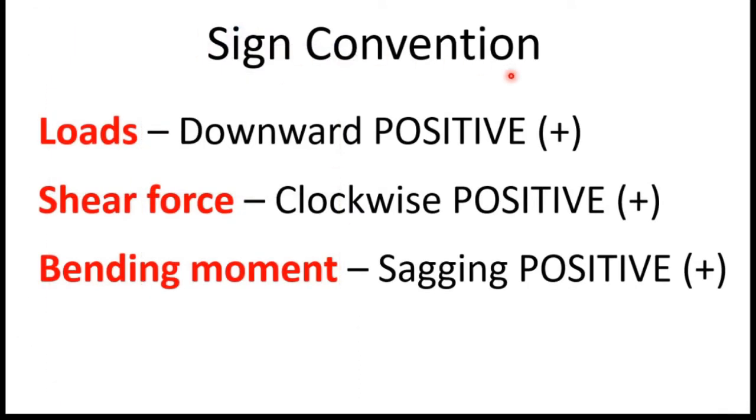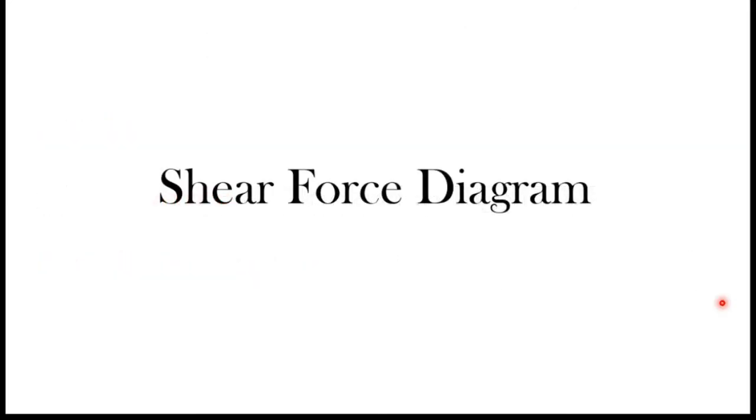Sign convention. So this is the sign convention I will use for loads downward positive. That means if the load acted downward, I will consider it as a positive force or positive load. Shear force clockwise positive, bending moment sagging positive. Shear force diagram.